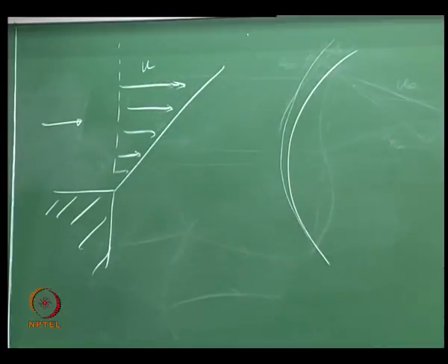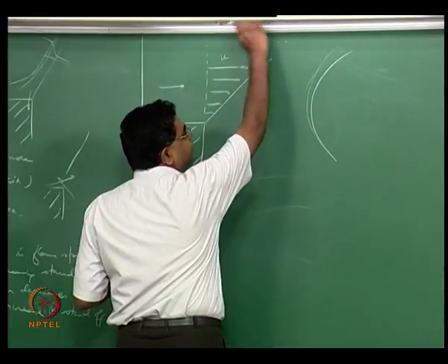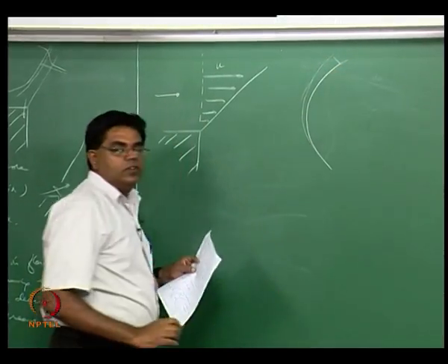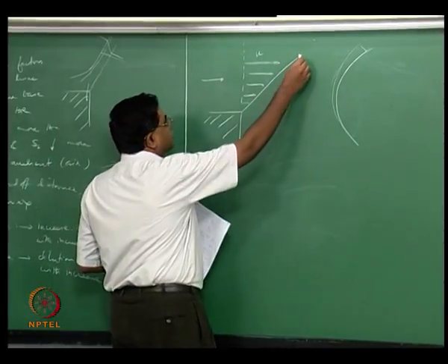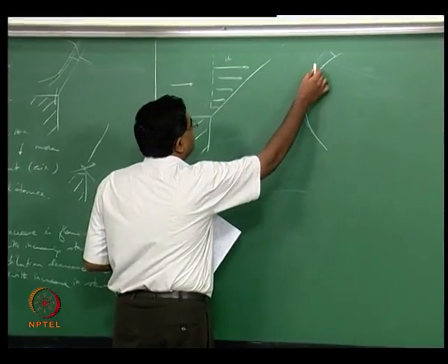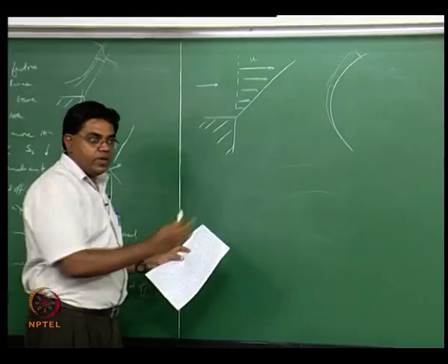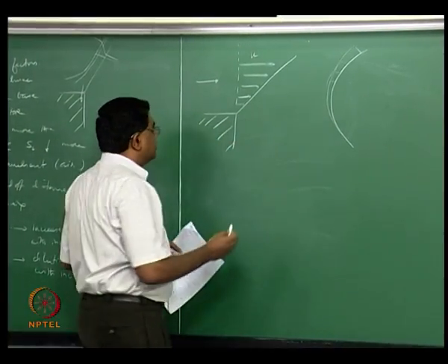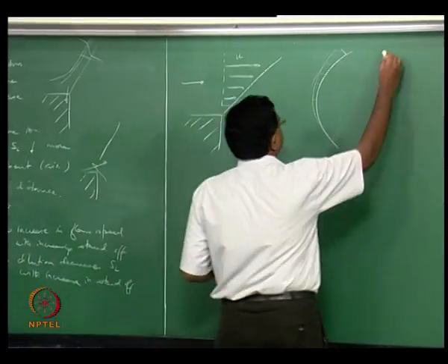Right, as it is over here, with respect to the free stream velocity, the flame speed is low, but the flow speed is actually decreasing linearly, and the flame speed is decreasing because of heat loss on the one hand as its proximity to the burner is determined, and because of the mixing, and we are now considering a fuel lean case.